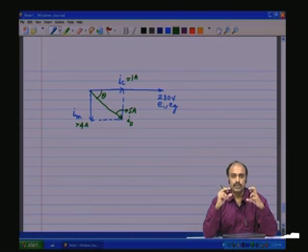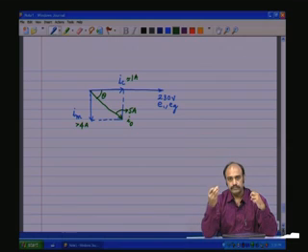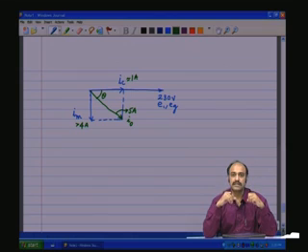There is only a portion of the flux that actually links between the two coils, and that is called the mutual flux. So, we have the leakage flux and the mutual flux, which results in actually lesser voltage being developed across the other windings in the core. Now, all practical transformers will have some flux which does not link the other coils in the core path, and they are called the leakage fluxes. And we will see how we try to incorporate the leakage flux component into the equivalent circuit model to have a much more complete picture of the transformer.